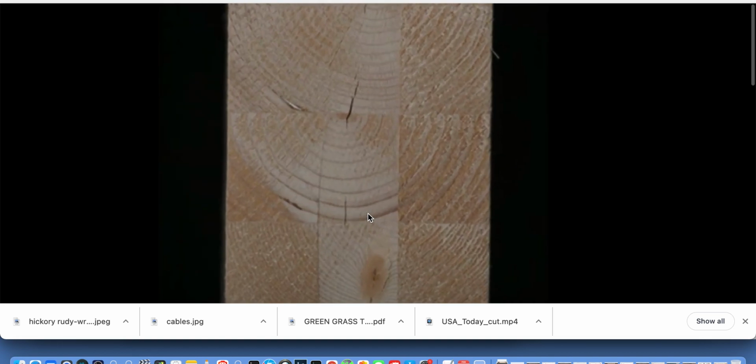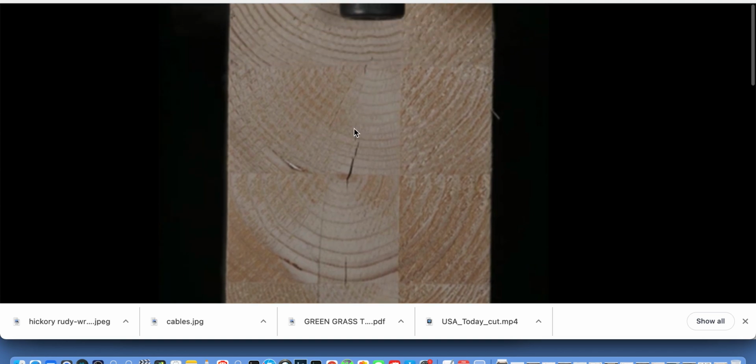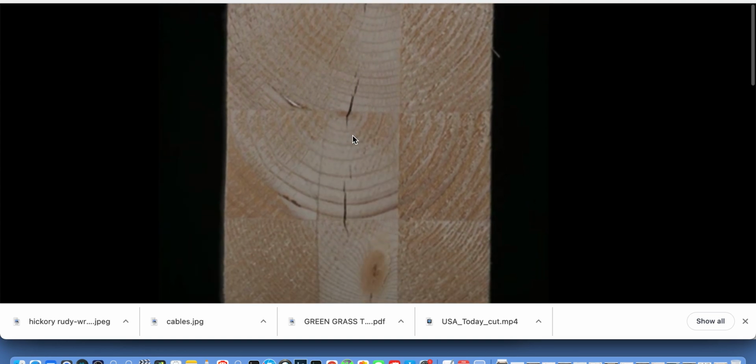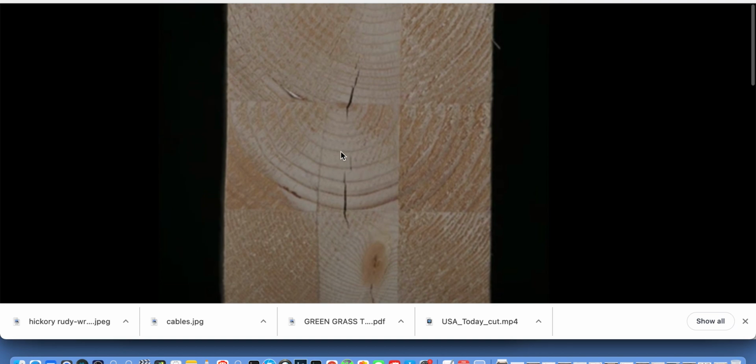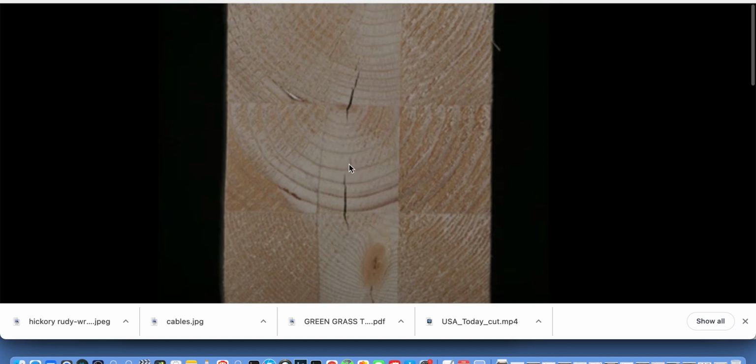Okay, there we go. So that's a larger stirrup, so you can see it can't stretch as much. It's just larger, so it fractured real fast. There's the largest stirrups here, and the tightest stirrups are down here. Let's go here. And there they did. I mean, they've already separated. Remember, the rule is once it's broken, it's broken. Then you have to look at the new connection, the new moment, the new point where it's taking up the load.